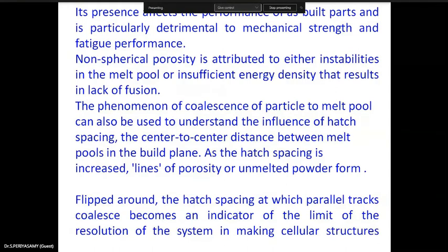Now the potential defect available here is porosity. Porosity is a common defect in selective laser melting. Because the powder consolidation process is driven only by temperature changes, gravity, and capillary forces without the application of external force, most of the time you may get porosity.